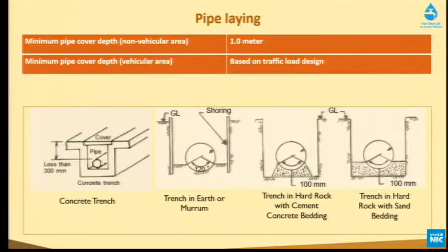If we have very narrow space and don't have space to lay deeper, definitely we can protect by putting a slab cover on that. Especially in rocky terrain, in some places I have seen pipes laid, even SWR pipe, and if there is some point load, it's going to fracture the pipe in the long run. So always recommend giving some sand bedding so that the bedding is smooth and the pipe is laid smoothly.